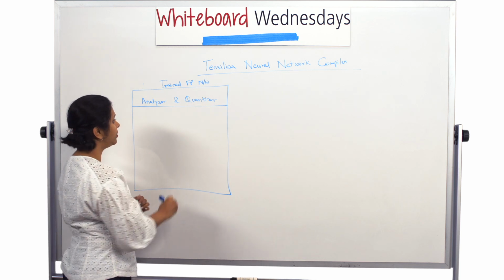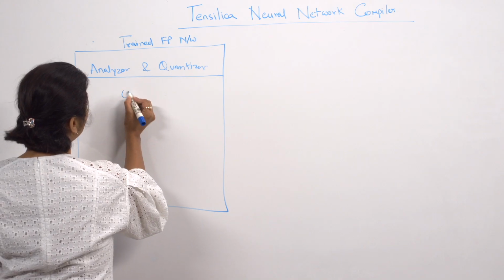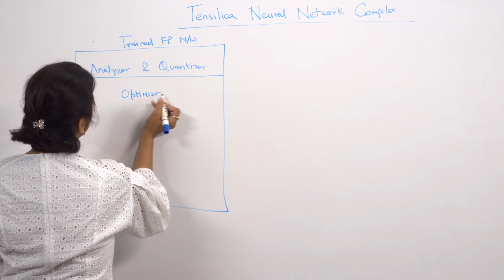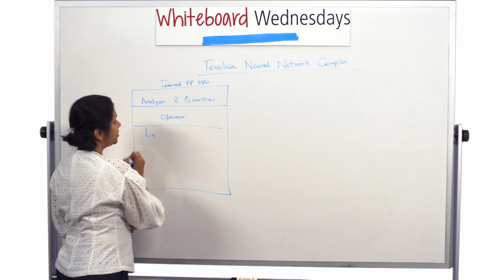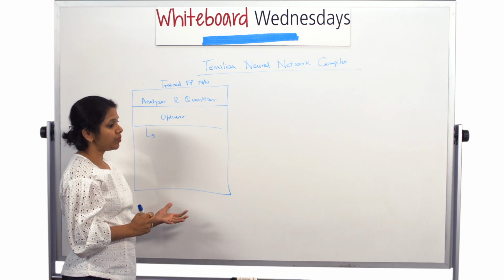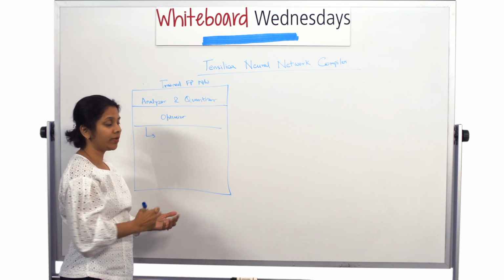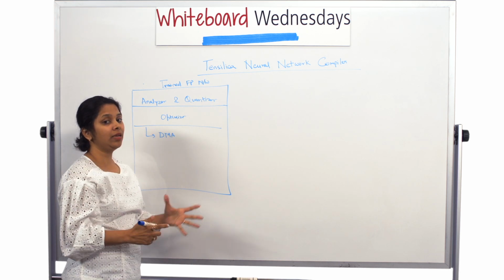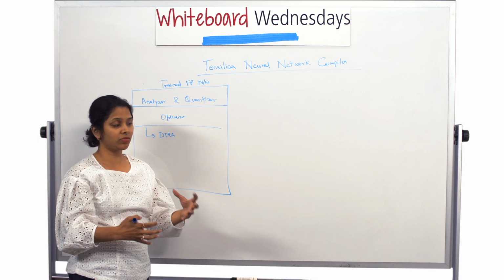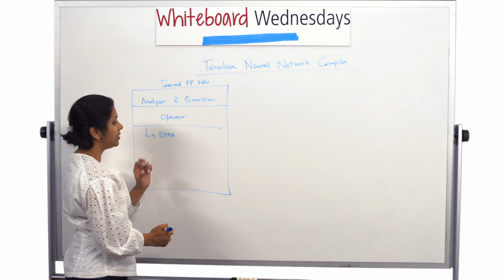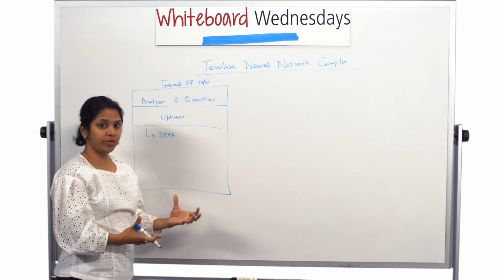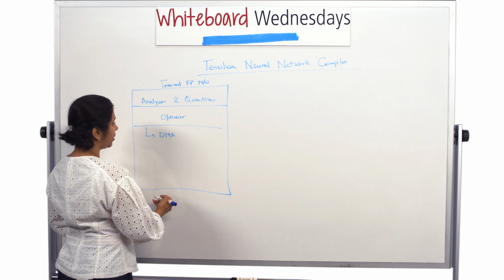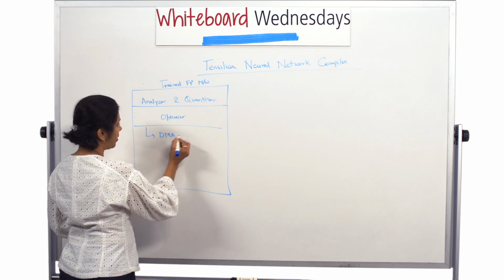Once the quantizer is done, it goes through the optimizer. The optimizer has several jobs. Some of them start with DMA management. All our DSPs and processors are enabled with integrated DMA. So we need the DMA manager to intelligently get data through the AXI interfaces from the system memory into the local memory, and understand how much memory is actually present, how much data I can bring, and how much I can do in parallel with the compute capability of that core. All that intelligence goes into the DMA management.